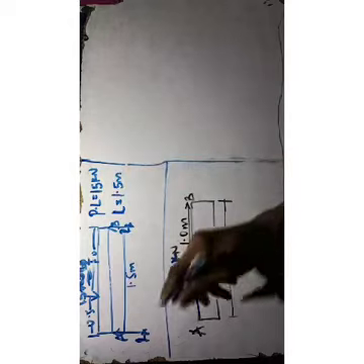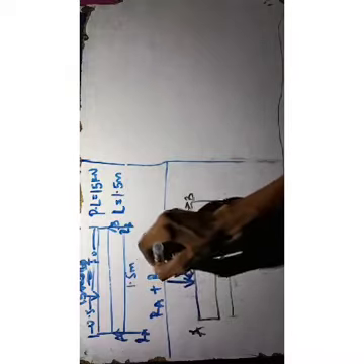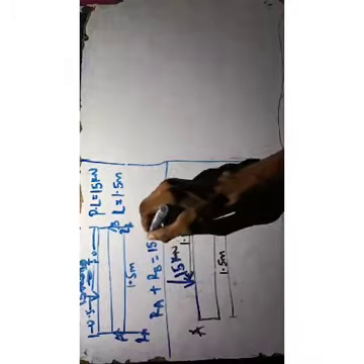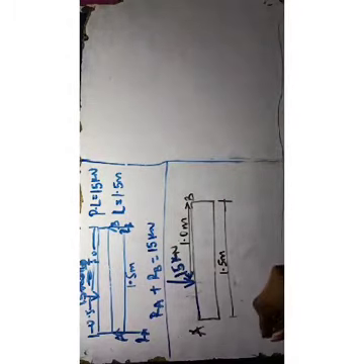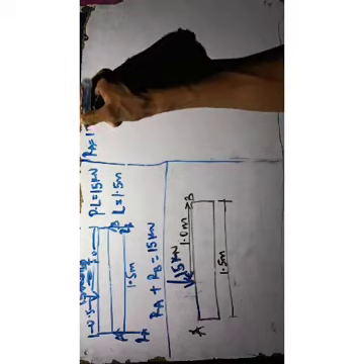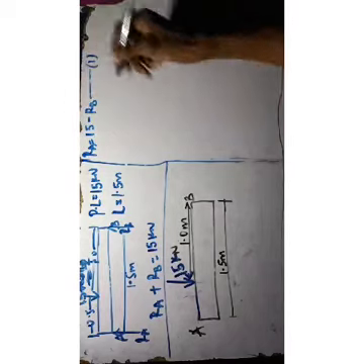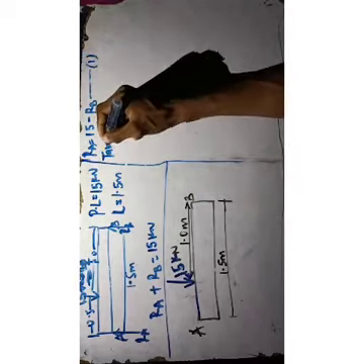So from here you can resolve first that your total force RA plus RB will be equal to the force, that is clockwise equals anticlockwise. That will be equal to what? 15 kilonewton. Then from there you can make RA, so you can say RA equals 15 minus RB, equation 1. So therefore you can take moment to get your RB.